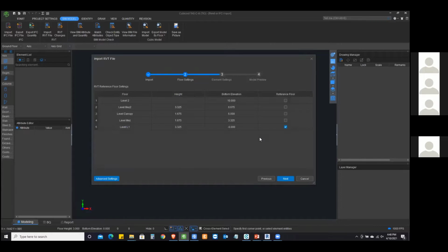Now, what's important to notice, as I mentioned before, is that you have to follow certain rules in order to fit that model in the software while modeling the Revit model. There's a guidebook, so you can follow that guidebook. For example, you don't have to use the same name for another material. Don't use this, don't use that. So it's just naming, and sometimes it also comes down to separating different floors for each one of these elements.